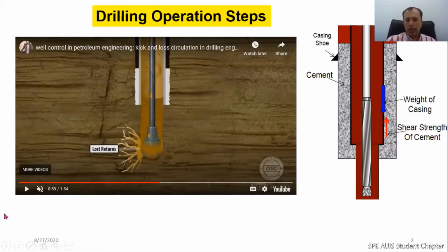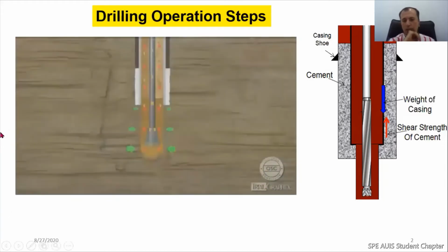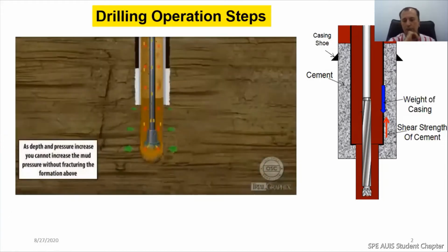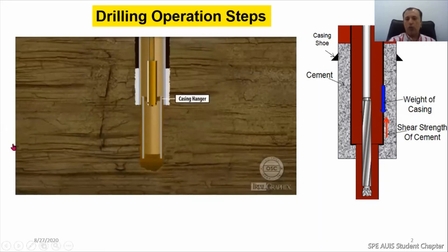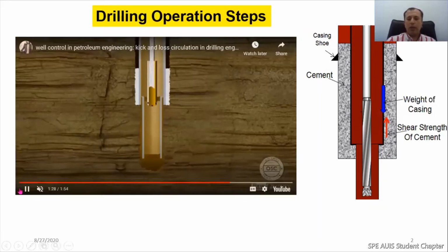What else do we have? Let's see. After fluid loss, we will face another problem, which is casing. We are gonna set up the casing down to make the borehole stable, so we'll not have a collapse in the weak layers of formations.